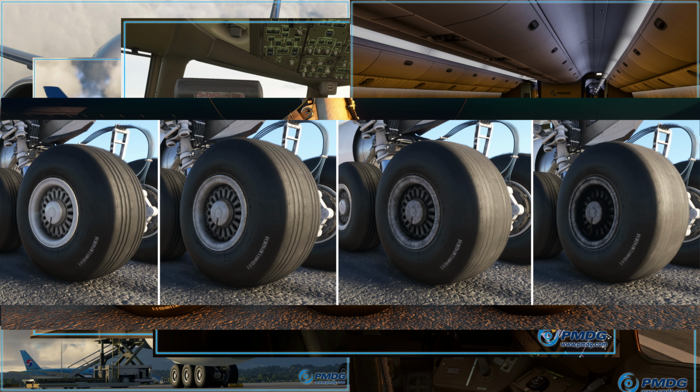Now, on this picture you can already see that wear and tear on the aircraft tires is modeled. Now, you gotta make a careful check on your walk around to make sure that there is no significant damage to your tires. Now, aircraft tires can take quite a bit of a beating, but nonetheless, you want to be careful that they are not overly worn, otherwise they can fail, especially when they're rotating quickly on takeoff and landing, and that is really not where you want a tire to blow up.